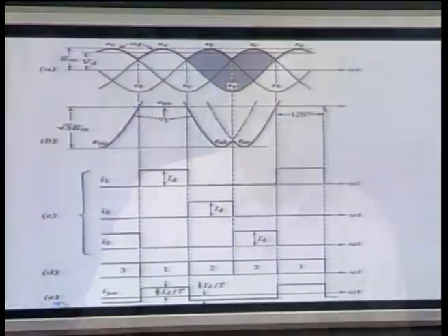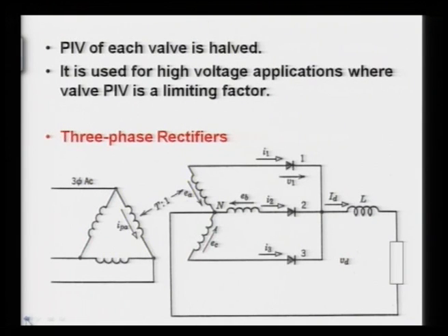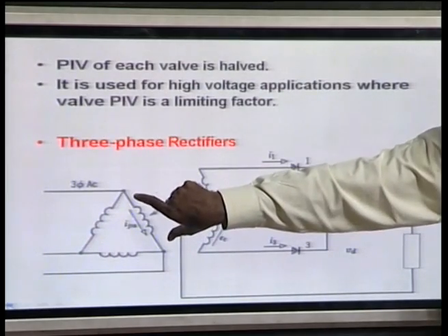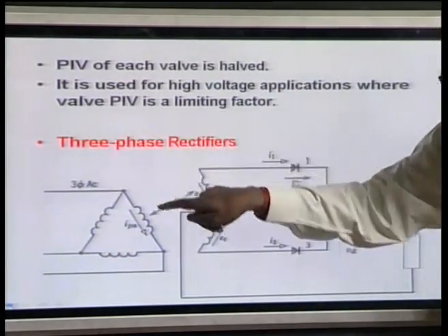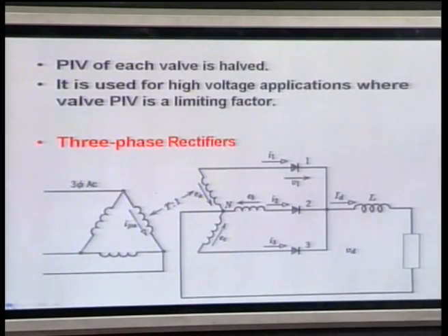But in this case, you will find the average value is 0, but it is not a perfect sinusoidal in the phase. If you convert it to the delta side of the transformer, the line side, just I want to explain that this is the phase current we are talking about. Now, for this current, this current minus this current will be this current, and then we will have the square wave output, and we can see that in the next term as well. So, in this analysis you will see what we are getting.